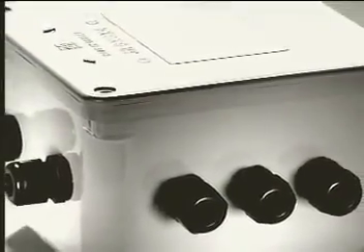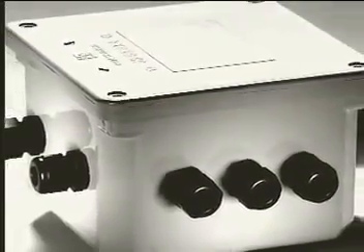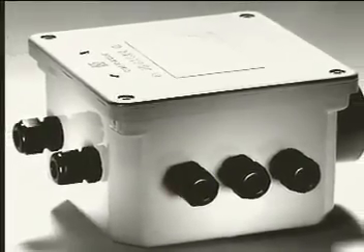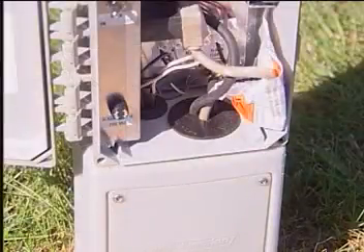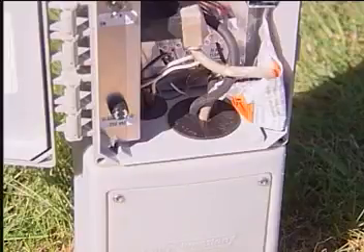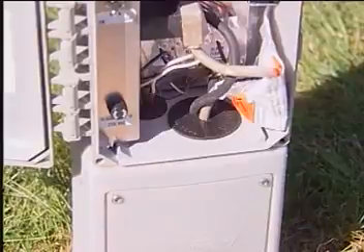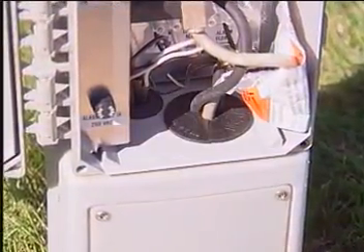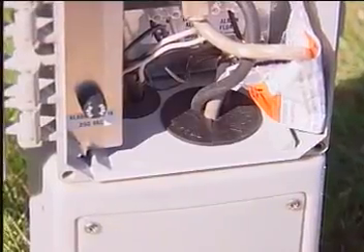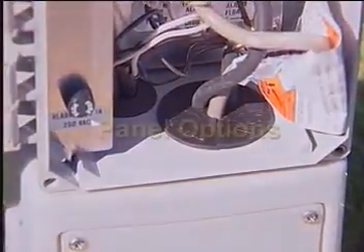An often overlooked but essential part of the control system is the junction box. The minimum acceptable NEMA rating is 4X, but again, check local codes. Since controls and switches will be working in a corrosive environment, all connections should be sealed with heat shrink, and cord connectors, if used, should also be rated to appropriate NEMA standards. For sealing conduit entrances, electrical sealing putty or pre-measured epoxy mixes are recommended.